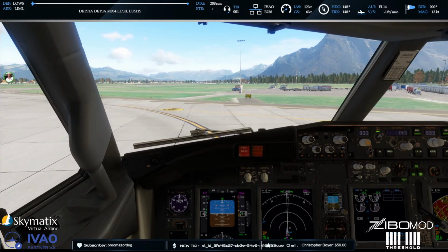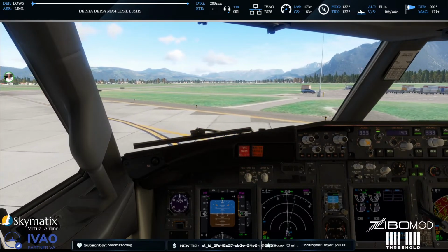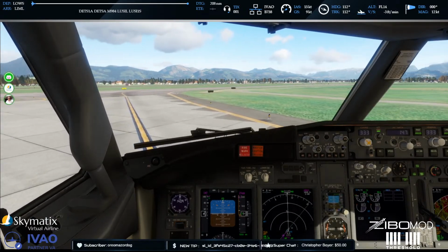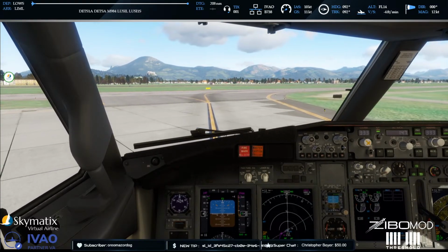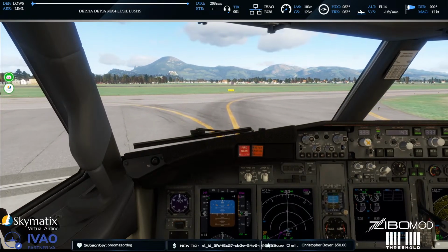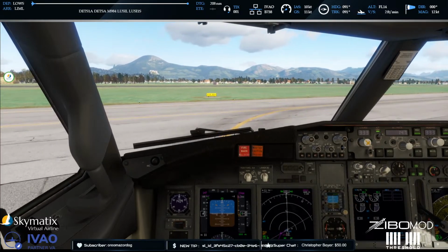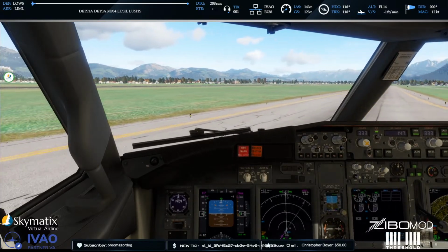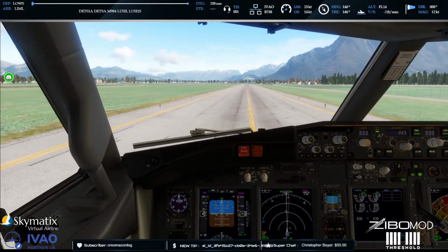Taxi lights on. He let it go up to 50, if I remember rightly. No, 29.4 I think it was. So he takes it up to the maximum it can go to on the air start. Okay, but that also depends on your atmospheric pressure at the time. He was obviously at Schiphol, which is under sea level, so he could push it up to 29. In most cases, in general flight, once you go a little bit higher in the atmosphere, at a higher elevation airport, you will never even get to 29. Yeah, I agree.